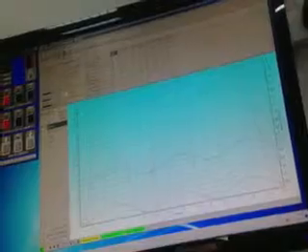Confining. Yeah, we didn't put confining, so if we had confining we would have applied the pressure again. So it was showing 0.3. Yeah, that's okay, but 0.3 is probably just some circulating air going on. If we were targeting 50, then you should see the 50. So I think in the specification, as long as it's plus or minus 0.5 kPa, we can tolerate the target.